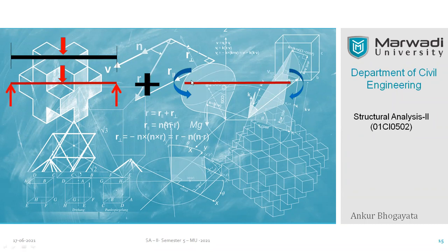Right? So now always remember that when you apply only moments, do not use any loading from the span in the original structure. Here you can see once you have already considered the original load, so there is no need to reuse it over here. Only use it once in the first structure itself and develop your BM diagram, and then only apply the bending moments which you have released, right? So always the diagram of the released structure because of moment will always be a rectangle.